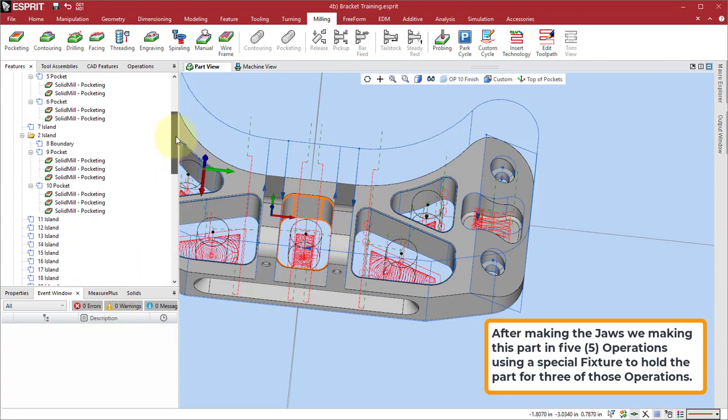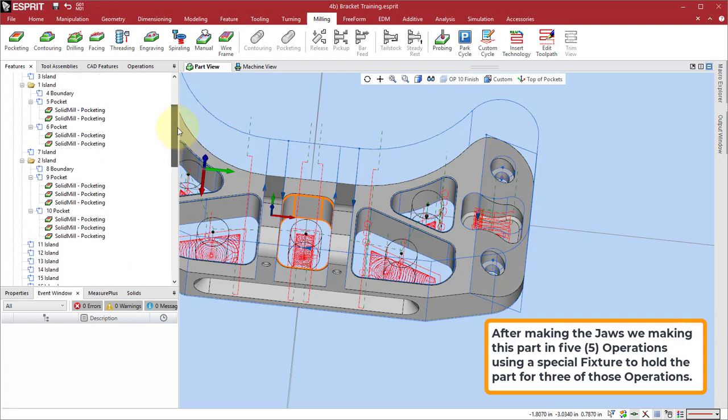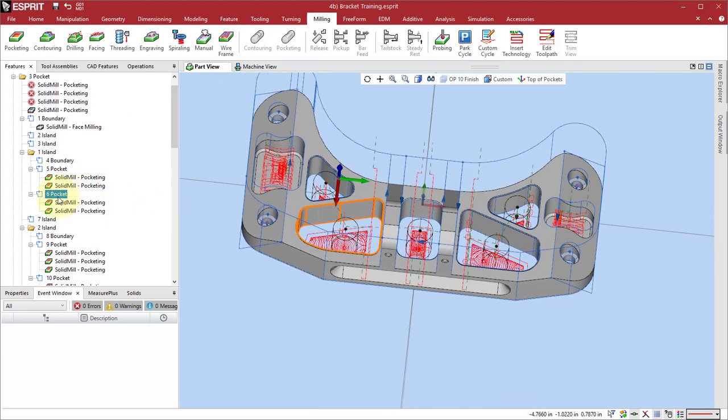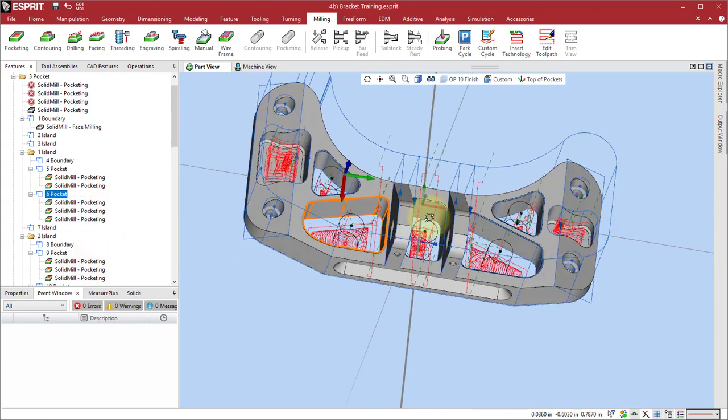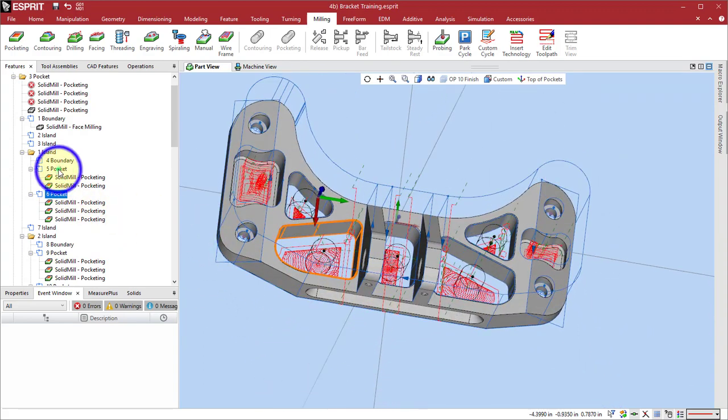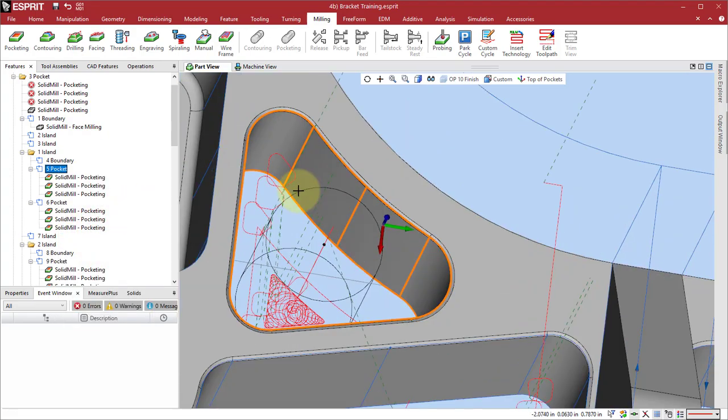Go back up towards the top to the other pockets. That'll be these here. This one was next. We right click and we paste it. There we get toolpath just in those corners. In this case, 1 corner. And then do one in here. Paste it. And now we got toolpath in those corners. Good.